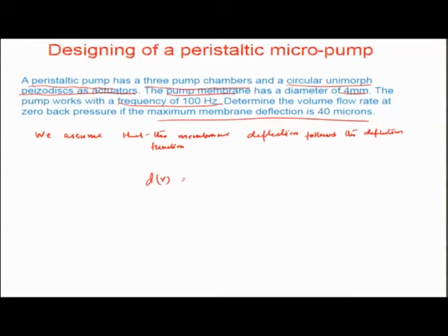d at certain radius, where d is this displacement. So, we were talking about a uniform displacement of the circular disk d. Okay. So, the d can be at various places from the center here to the sides, and these are different d's. Okay. So, this d function as a function of the radius here is related to the maximum deflection which is there in the center.